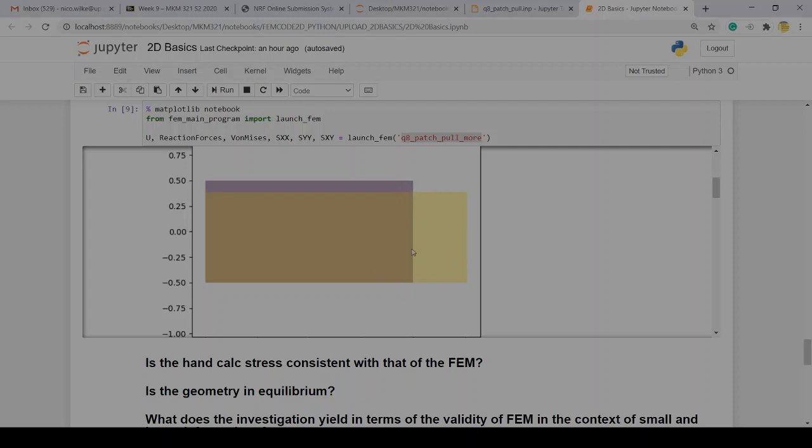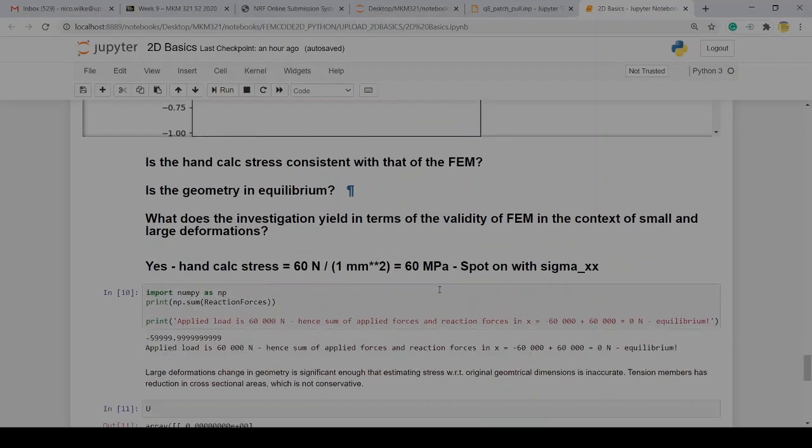So what do we expect the stress to be? Well, I expect it to be similar to what we saw before. The only difference is it's now 60 kilonewtons as opposed to the 60 newtons that we applied. But I would still expect to see something in the 60s because of this original area. If this was the area that was used, then the stress would be something different, a little bit higher than 60 because this area is smaller. So this is important to understand, okay?